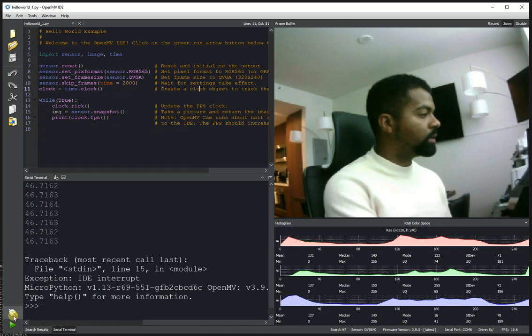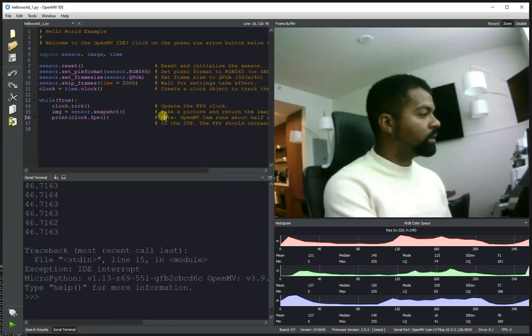So let's disconnect from the OpenMV Cam right now. And if the Wi-Fi shield is running, you're going to see this option for a little Wi-Fi symbol down there. So you're just going to click that, and that tells you the OpenMV Cam is now found on the wireless network. And we can see the name we put in, OpenMV Cam H7 Plus. We see the IP address, and we also see the port we're going to use. And we can click OK.